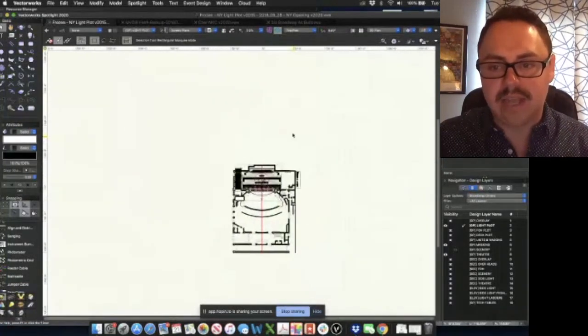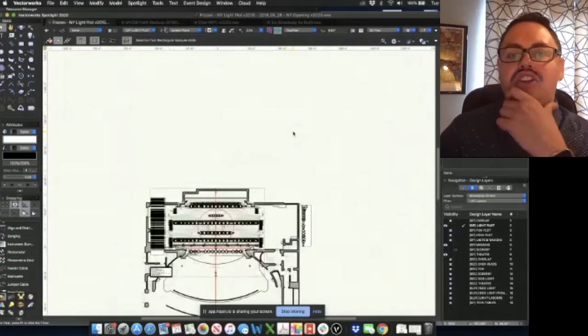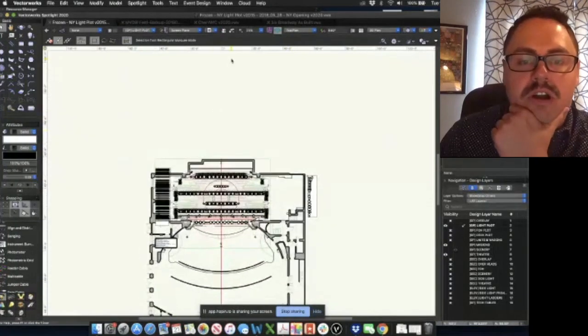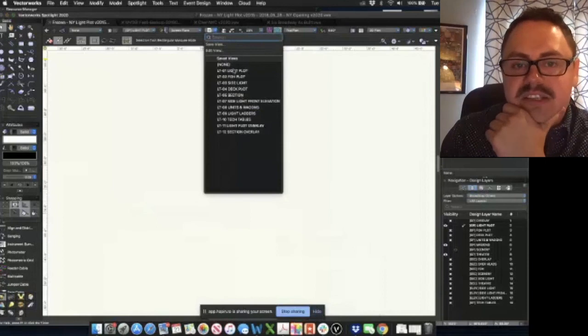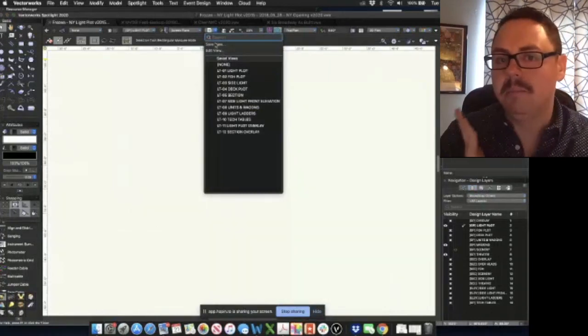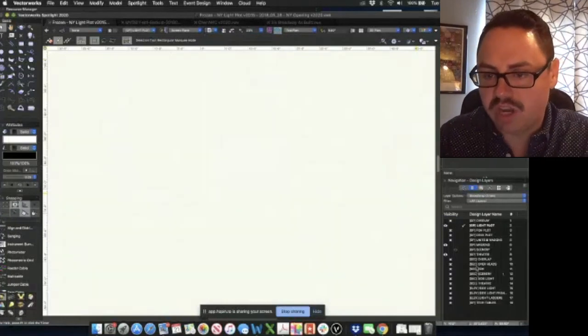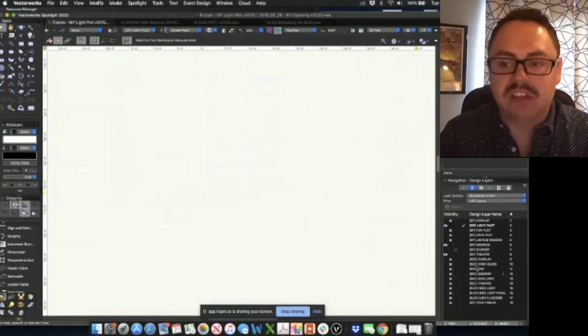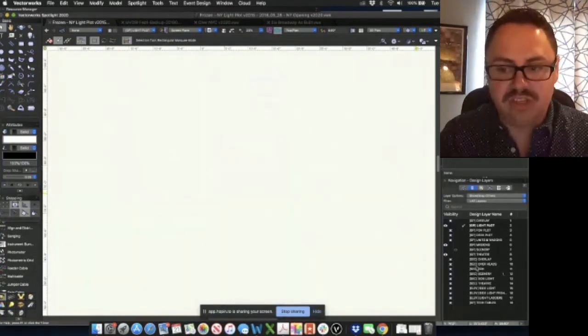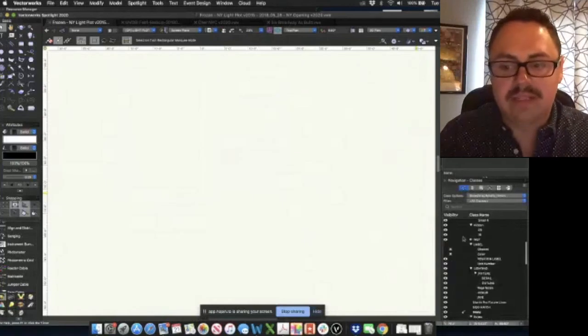These, once again, have a lot of information. If you guys have never used them before in Vectorworks, they have these things called saved views. My favorite thing I've ever learned. If you look over on my drawing layers, it's a lot of layers there. And classes, I can scroll for pages. Everything is filtered down.